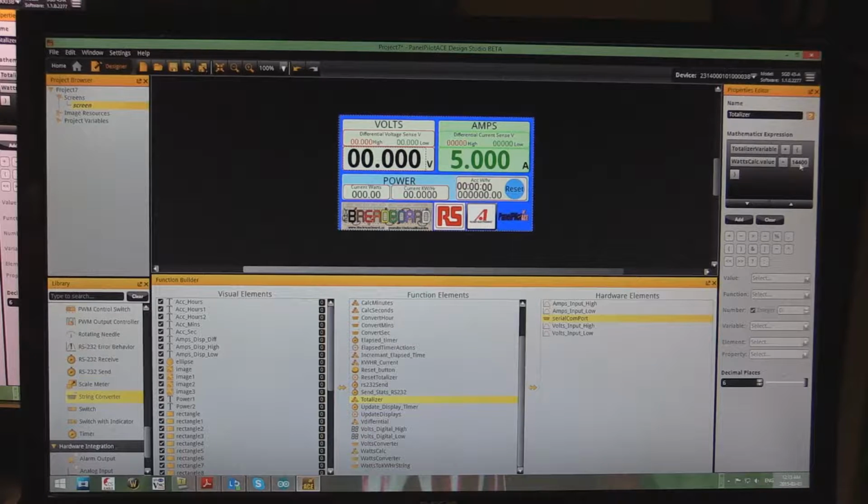14,400. And the reason it's dividing it by that is because we're slowly accumulating the amount of watts, and if I'm actually instantaneously using 20 watts, then the watt hour should be showing after an hour 20 watts as well. So because I'm sampling at 4 times a second, I have to divide it by the equivalent of an hour, which is 14,400 samples, and that allows it to be displayed properly. Now at the bottom here, because that's such a small number, I've set the number of decimal places to 6, so that you will see it accumulating even if you've only got a few milliamps flowing through your load. And as you saw before, that then gets assigned up using the every quarter of a second, it's getting updated into the display.